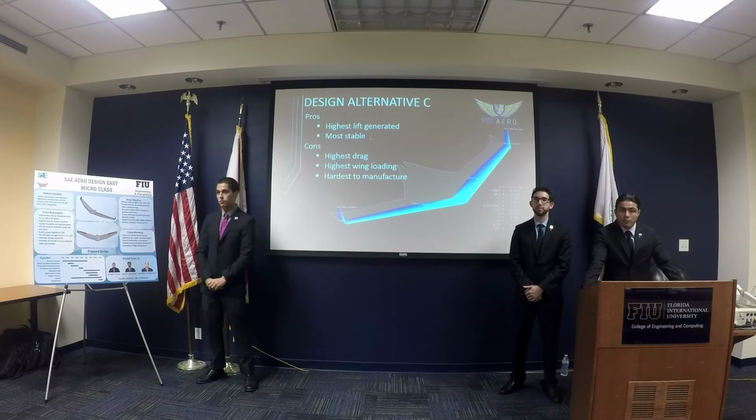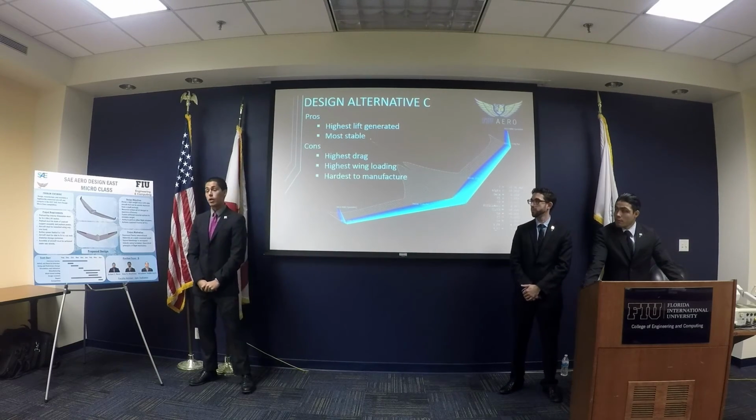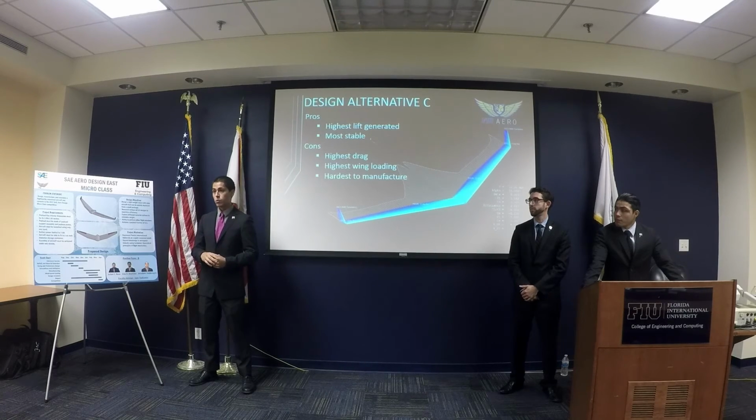Your propeller's in front? Right now we're having a tractor propeller configuration. According to sources, it was the most efficient one. We are thinking of going pusher only if our center of moment is unstable. With our modular design, we have the luxury of changing and shifting things around depending on the flight characteristics we want. So that's something for the future, tractor versus pusher.